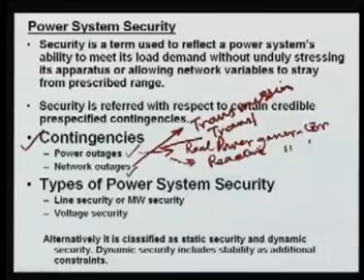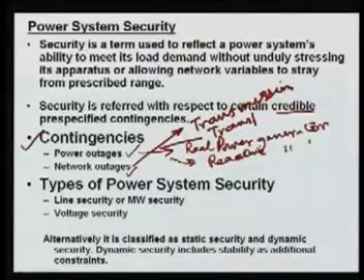As you know, if a power system has thousands of buses, there may be several thousand elements in the power system, including transmission lines, transformers, and generators. So the number of contingencies in any power system is very, very high. So for which contingencies are we talking about? It is one contingency, two contingencies, or it may be several. That's why here it is called the credible prescribed contingencies, meaning those whose possibility is very, very high, and at the same time, they are very, very critical.